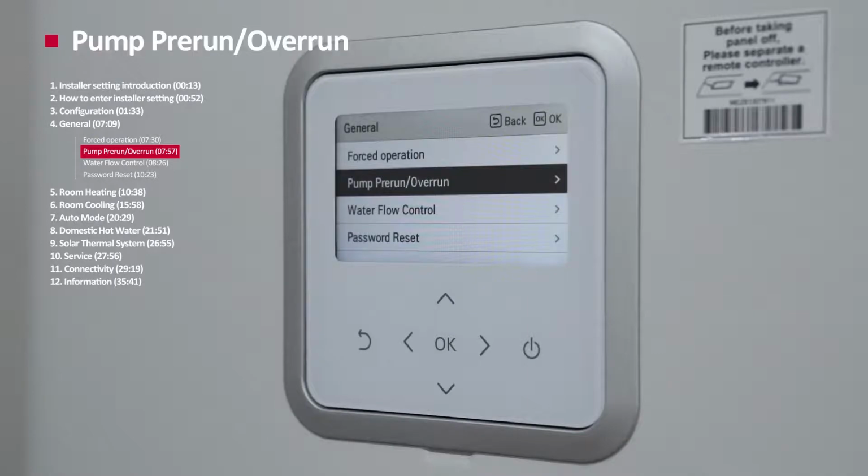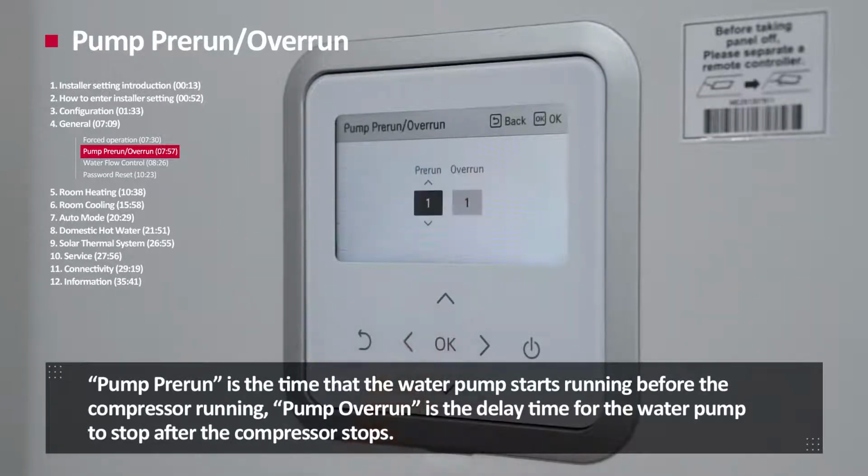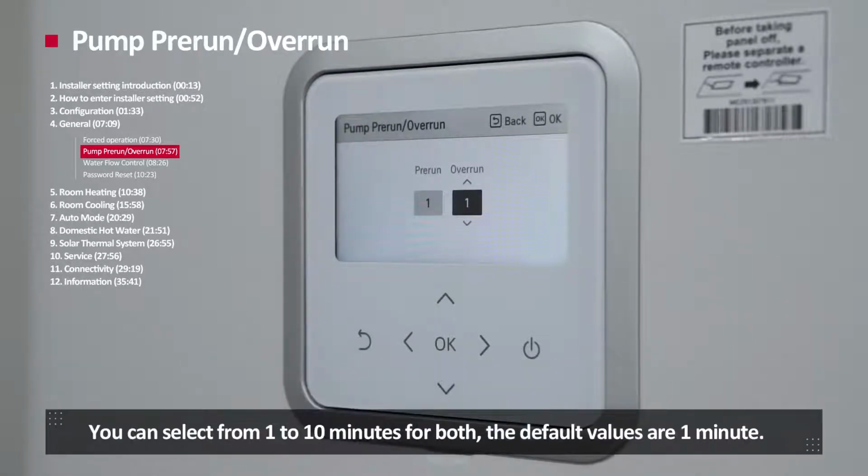Pump pre-run, overrun. Pump pre-run, overrun sets the delay time of the starting and stopping of the water pump operation. Pump pre-run is the time the water pump starts running before the compressor runs. Pump overrun is the delay time for the water pump to stop after the compressor stops. You can select from 1 to 10 minutes for both. The default values are 1 minute.